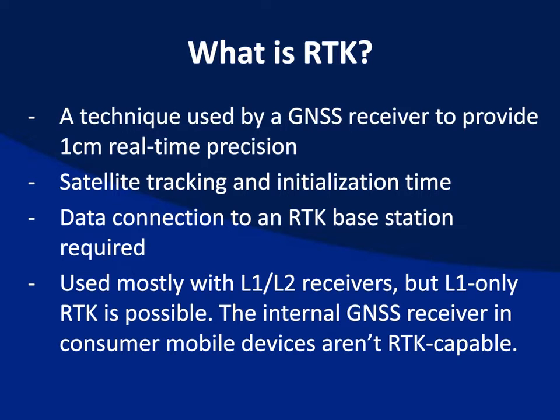But you can find lower performing, lower cost L1 RTK receivers, and I played around with those 5 or 6 years ago when Magellan, which is now named Ashtech, came out with an L1 based RTK system. There are several of them out there now, but the challenge with those is the initialization times are typically much longer, and that may be okay in agriculture or some areas where you have an open view of the sky.